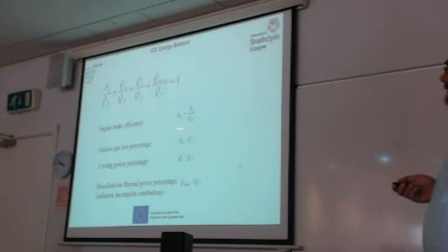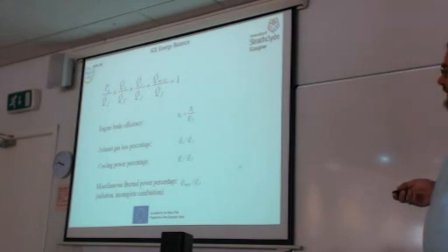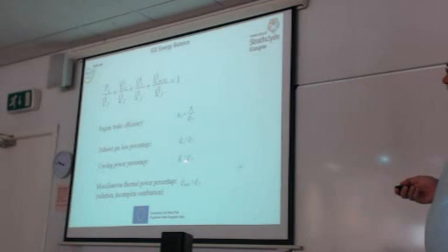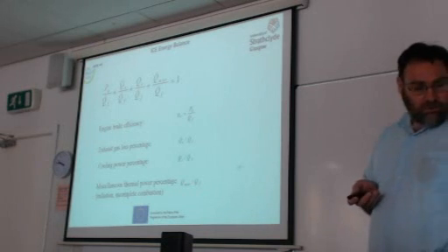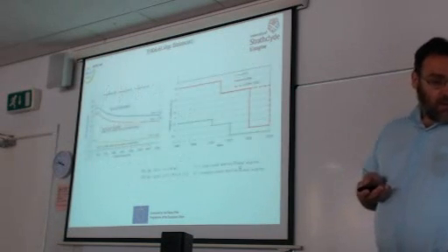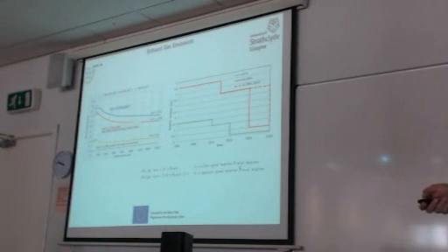Typical values for the marine engines generally: the brake efficiency for large engines is close to 50% or a bit above 50%. 25% we expect for the energy exhaust gas losses, and then 20 to 22% or 24% expected for the cooling power, and less than 1% expected for the radiation or miscellaneous power.